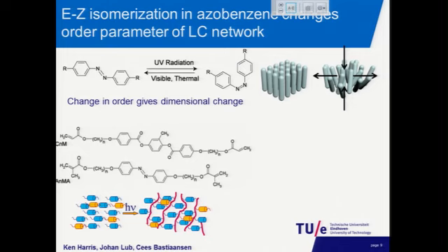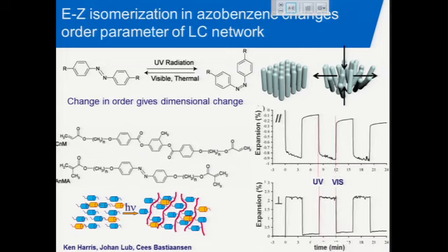We take our liquid crystalline diacrylate, and we just add, for instance, 5% of this diacrylate containing this azobenzene unit. So you make just a homogeneous blend of these two materials, and they are brought into this polymer network.